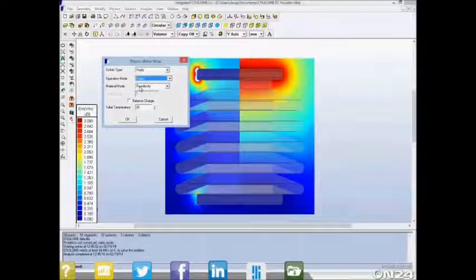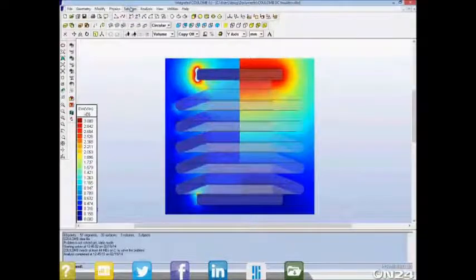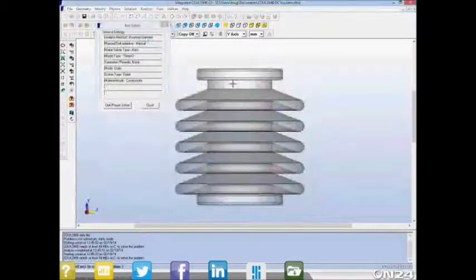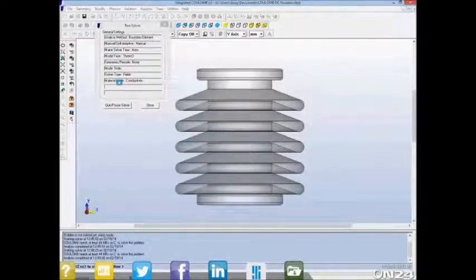So if we consider that's going to be the field distribution due to the permittivity as soon as you turn on the high voltage, the question is, what does it tend towards over time? And that's what we can study by setting the material mode to conductivity. When we get the conductivity solution, we'll see what happens an hour, 2 hours, 3 hours after you flip the switch.